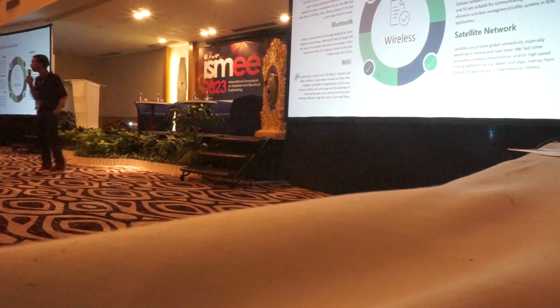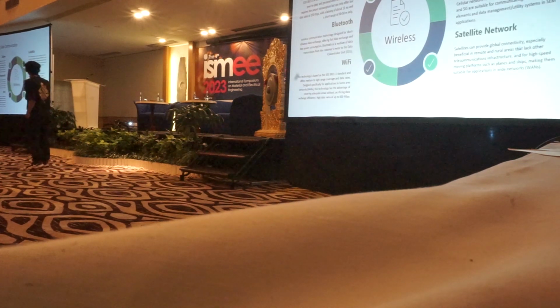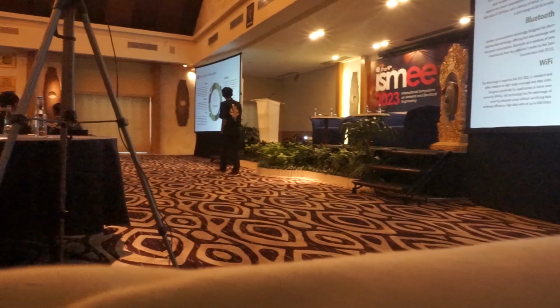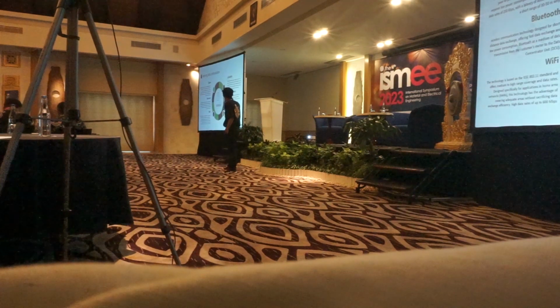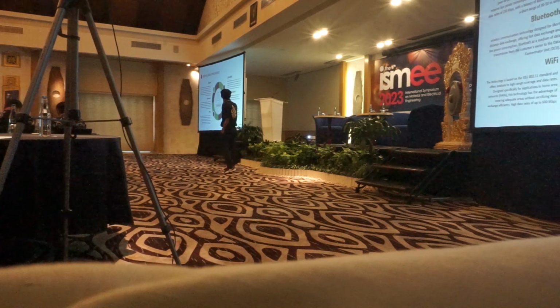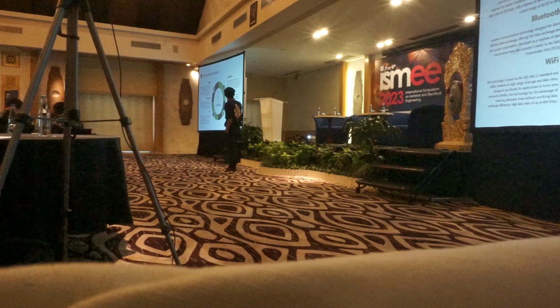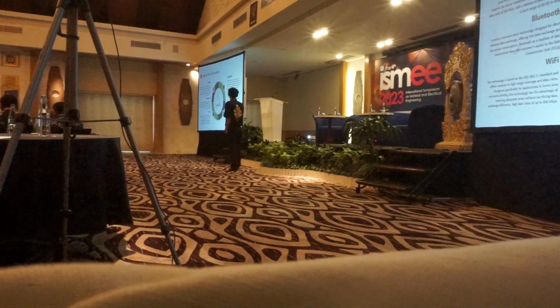And then we have LoRaWAN with a comprehensive range coverage up to 15 km in rural areas, low power consumption, affordable cost, and low data rates with a low maximum bandwidth of about 5.5 kilobits per second. LoRa cannot transmit audio or video. It can only transmit simple information such as sensor values.